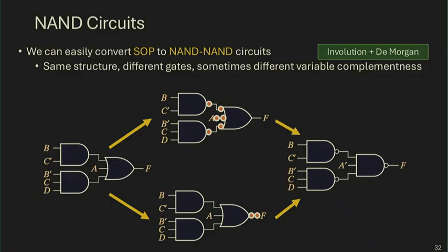And some people memorize this as a rule, which I would really recommend against. Some people say, well, the way we do it is for a two-level circuit, we don't flip the variable over here, we flip the variable over here, we just replace everything with a NAND gate, and then that gives you a correct circuit. That is true. That is a correct conclusion. But I expect you to be able to do the more manual analysis so that you can handle a wider range of circuit conditions.